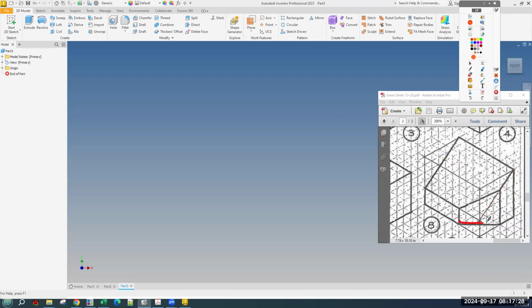And then we'll deal with this front corner, which might be a little tricky if you're not sort of thinking 3D yet. And our first sketch is going to be 5 across the bottom, 6 up the back, 2 up the front, and then connect. So 6, 5, 2, and extrude all the way across, which I think is 8.